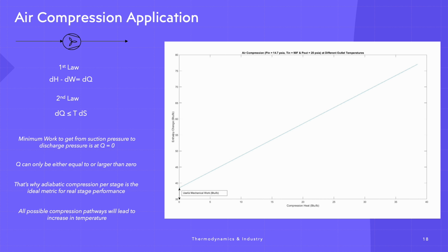That's why you need to compress the air not only to get its pressure higher, but on top of this to overcome the friction within the machine that's already built in because of the velocity differences, or basically the momentum difference between the gas and the rotor and the stator.